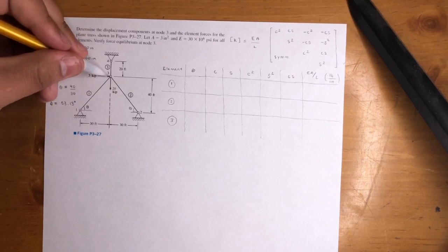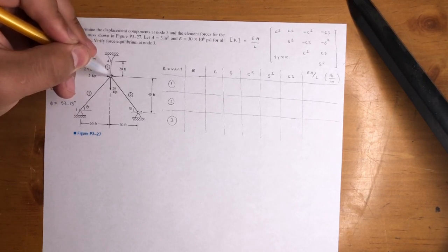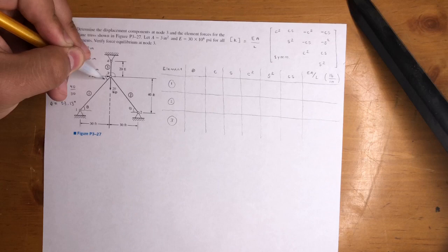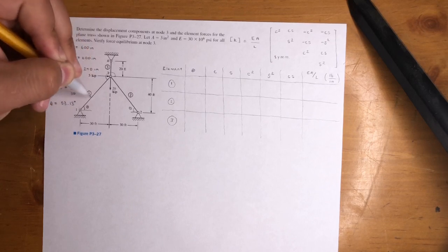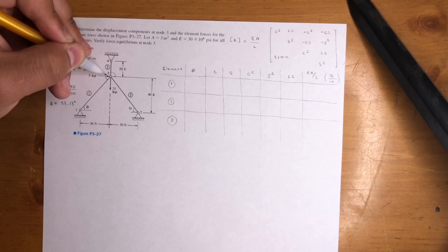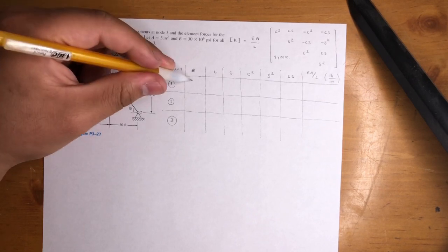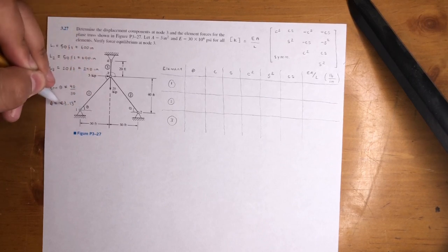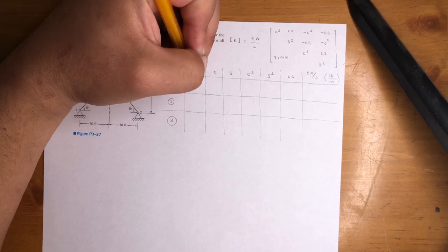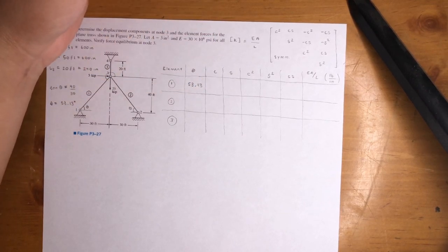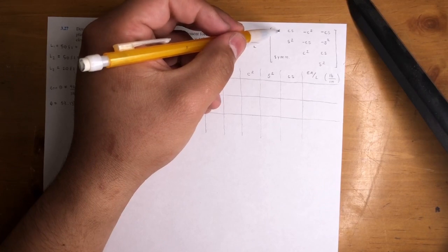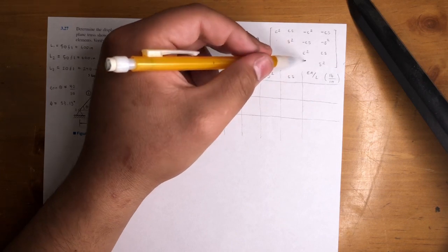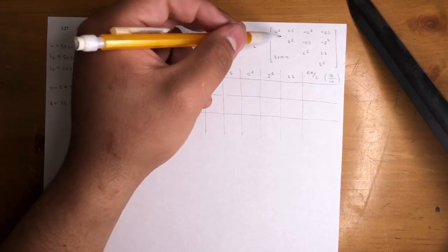Now, if you wanted to go from 3 to 1, this would have been your positive x-axis, and you would have done 180 plus 53.13, because this angle is also 53.13. Trigonometry. So it would have been like 220, 230 something, whatever it is. That would have been your angle. But because we're going from 1 to 3, our angle is going to be 53.13. And none of the answers are wrong, because this matrix is symmetrical: c squared, cs, cs, s squared, and same thing here, c squared, cs, cs, s squared. These 4 would just switch with these 4, but they're exactly identical.